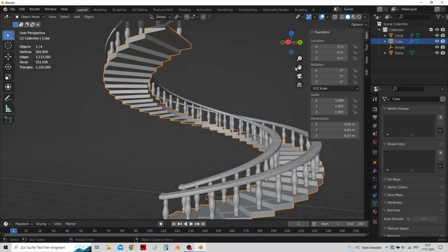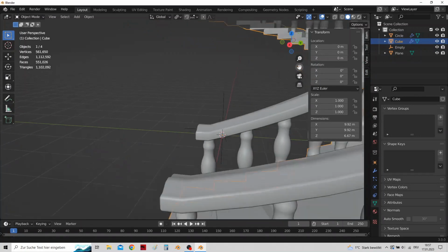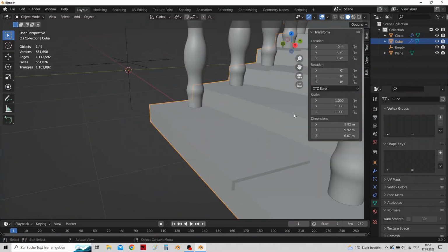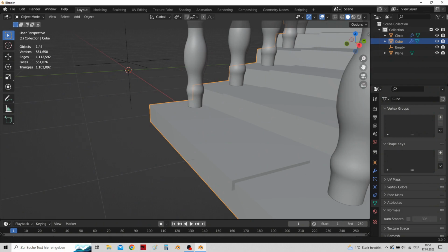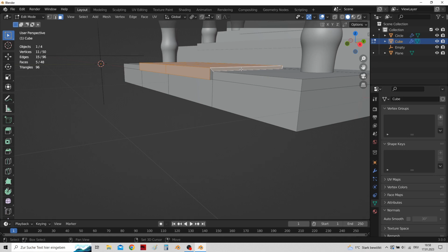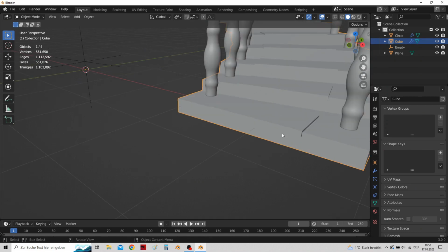But the whole thing in gray seems a bit boring and not so satisfying, so let me show you how to add some colors as a final step. Switch to edit mode again by pressing Tab, and by holding Shift and left-clicking, select all the faces of our carpet. Be sure that you are in face selection mode, which can be selected by pressing 3.